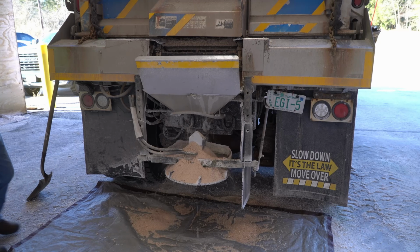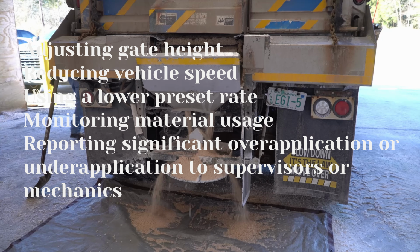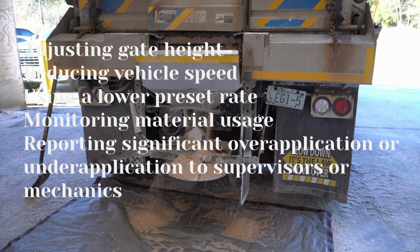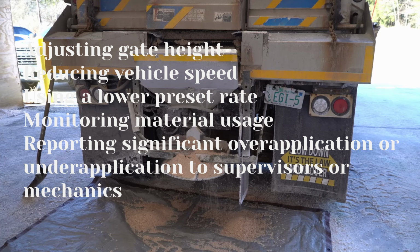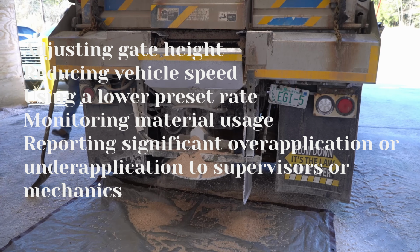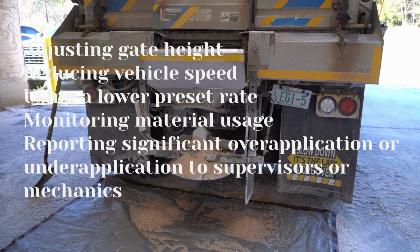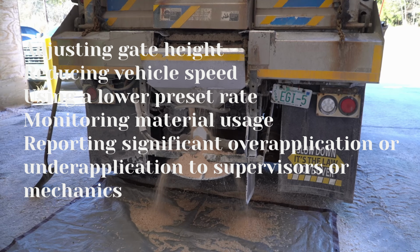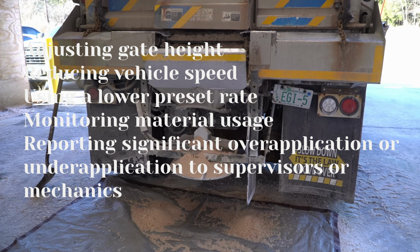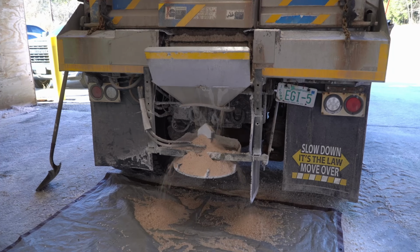Depending on agency policy and equipment design, this may include adjusting the gate height, if permitted, reducing vehicle speed where appropriate, using a lower preset application rate, monitoring material usage more closely, or reporting significant over-application or under-application to supervisors and mechanics. Even on computerized systems, operators should continue using observation, judgment, and field awareness to help ensure material use remains reasonable and effective.